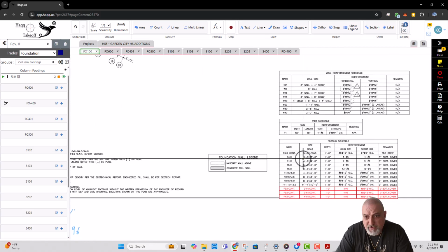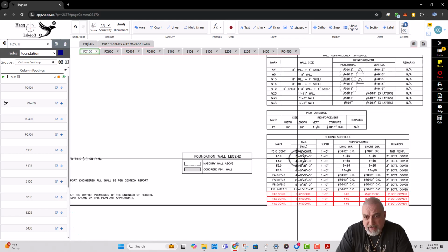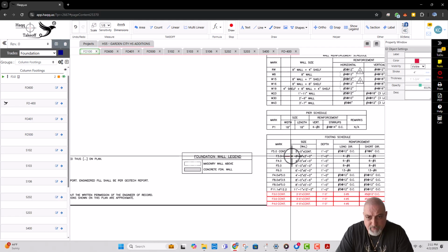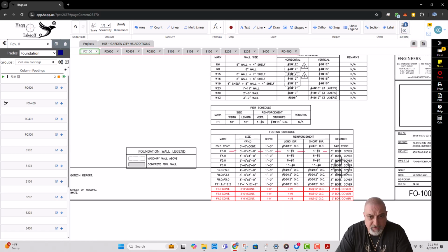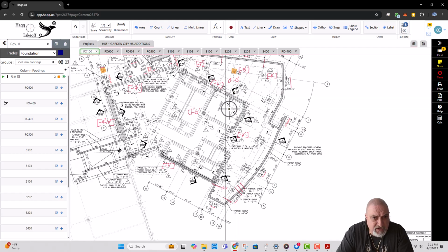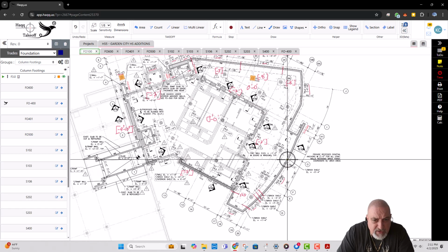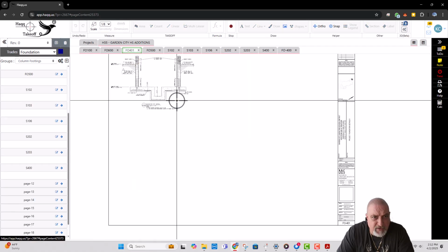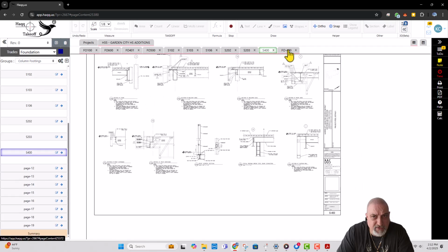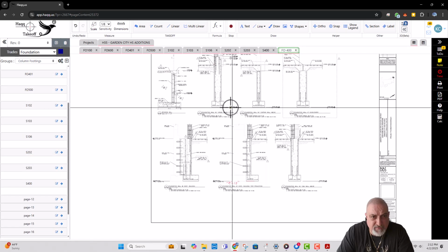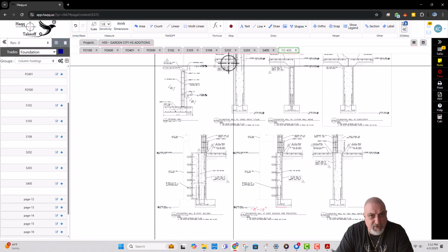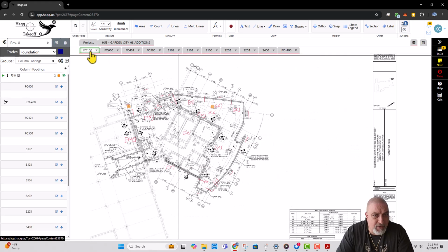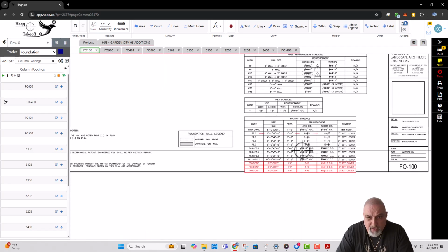Before we go for the next footing, let's add the reinforcing. It has number 5. We did this, right? Number 5, long direction and short direction. Do I have any section through column footings so I can see the reinforcing? I don't think so. F401 doesn't give you a section through footings. F400, no, these are not through column footings. This is a retaining wall. These are all wall footings. Okay, I was worrying about if there's hook bars at the ends.